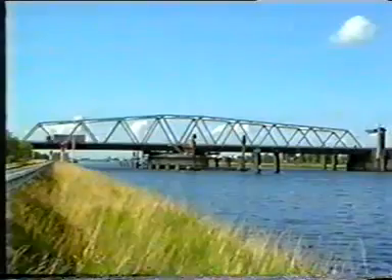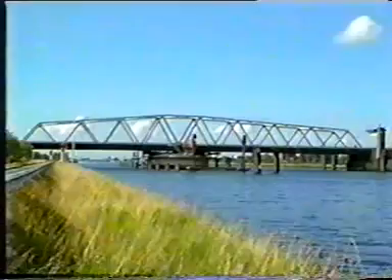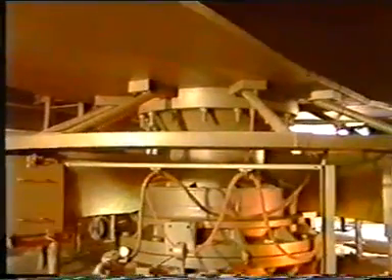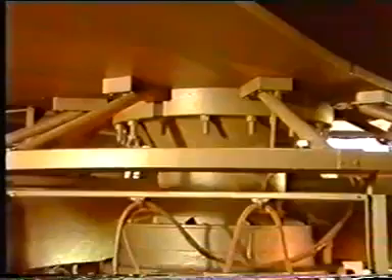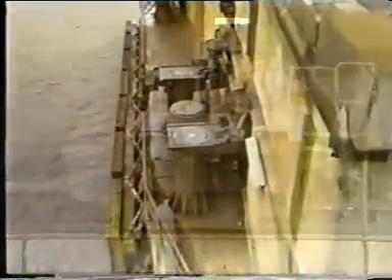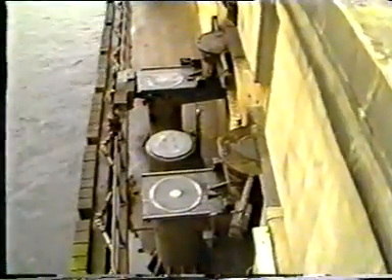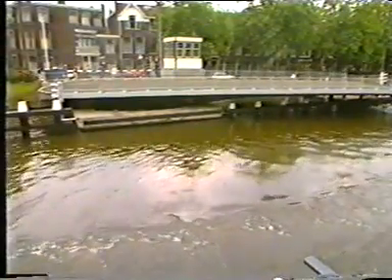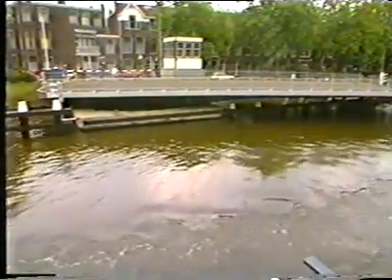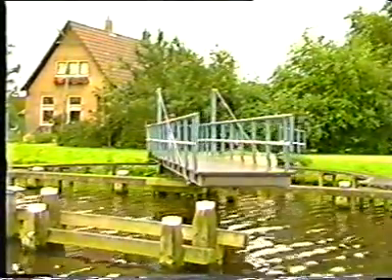A swing bridge consists of a steel structure with two equal or unequal leaves, supported on one point of rotation, a drive, and the end supports, including a raising device. Counterweight is only necessary in asymmetrical bridges. A plate girder as main girder can be chosen, or a simple cable-stayed girder.